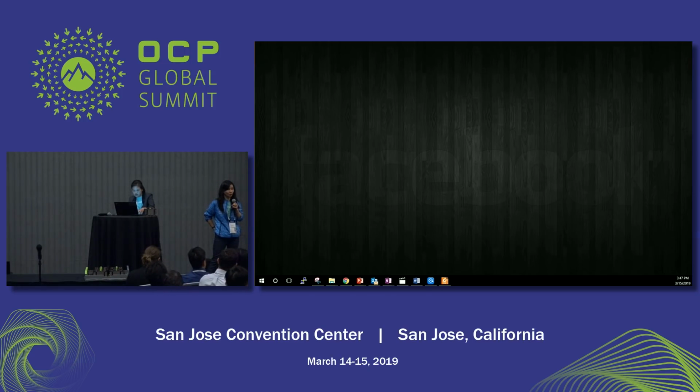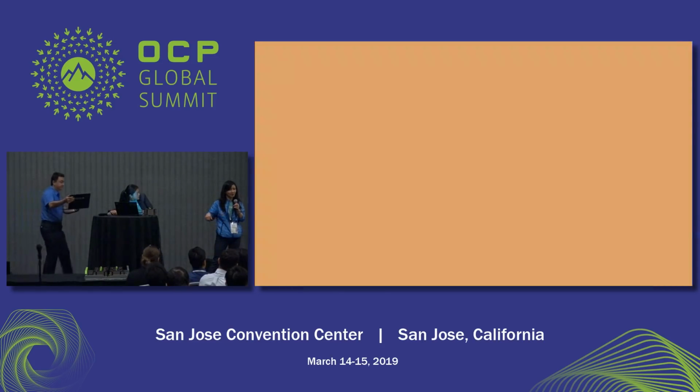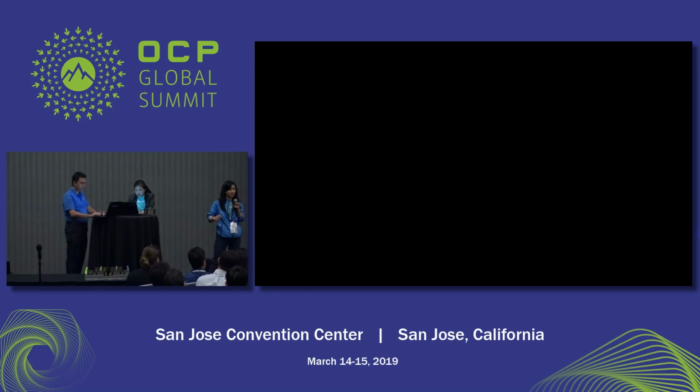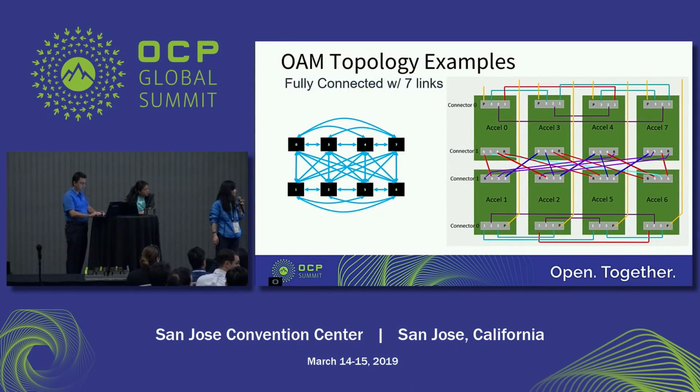What I can tell you is, for example, with the best material, running at I think 25 or 28 gigabit, it is about 1 dB per inch loss. That's Megtron 7 or equivalent PCB material. And the longest length for the fully connect is 15 inch. This is what I can tell from the baseboard. And then from the module side is about 2 to 3 inch total trace length. And then together with the connector, depending on your speed, the connector might have some loss.